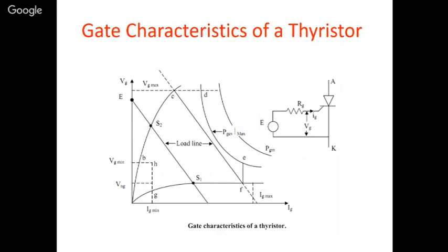That may be a thyristor with a motor control, or it may be a FACTS device. So that is operating at very high voltage and current. As I already told you, 5000 amps may be flowing, or it may be a voltage like 10 kV. For a drive application, it is a 440 volts, 3-phase supply with some 15 amps. The microcontroller is at a very low level, 5 volts and a few milliamps.